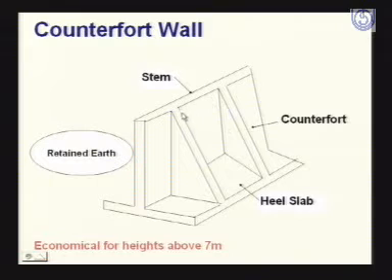Similarly, this stem panel is also fixed here, here and here. So this stem as well as the heel slab is now fixed on three sides and free at one edge only. This stem is free at this edge, and the heel slab is free at this edge.